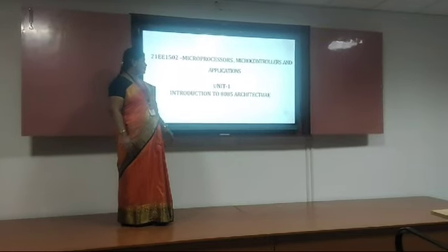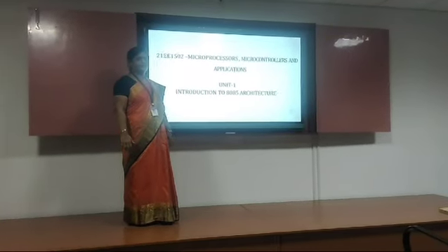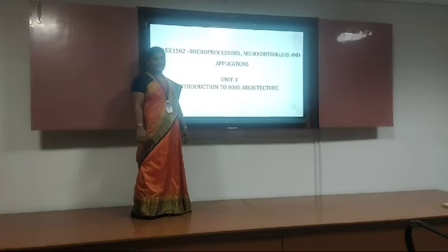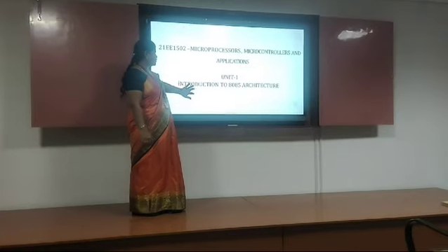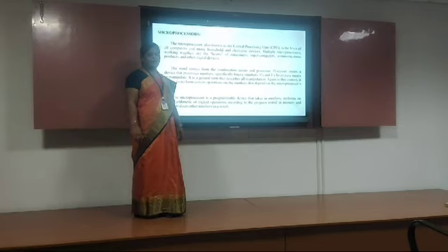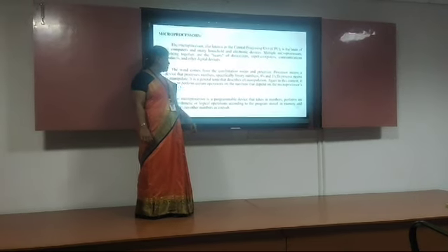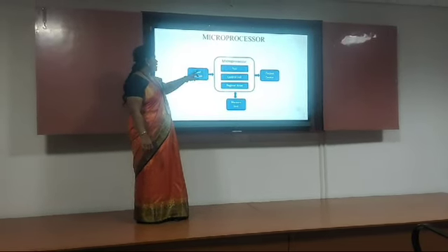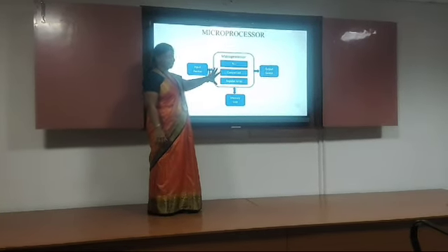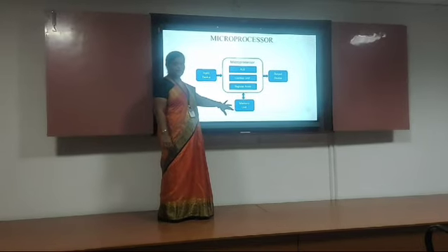Very pleasant morning. So in this session we are going to discuss the introduction to 8085 architecture. So what is this 8085 architecture? Actually it is a microprocessor. We call that microprocessor an 8-bit microprocessor. So we have three main sets in this. We have an input device, a microprocessor unit, and a memory unit separately.